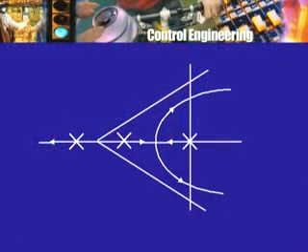By simply looking at these three poles, no zeros, I know that for a large enough value of k, the system will be unstable. Now, such a conclusion is really a marvelous conclusion that we can draw, provided of course one has studied the root locus method. By merely looking at the pole zero diagram, you are able to say something. Of course, one can proceed a little further.